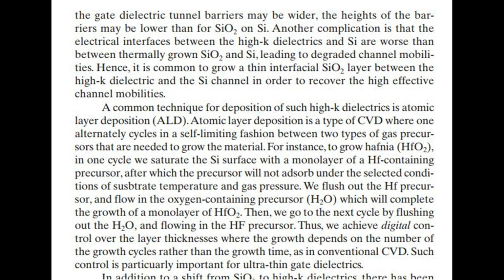Then, we go to the next cycle by flushing out the water, and flowing in the hafnium precursor. Thus, we achieve digital control over the layer thicknesses where the growth depends on the number of the growth cycles rather than the growth time, as in conventional CVD. Such control is particularly important for ultra-thin gate dielectrics.